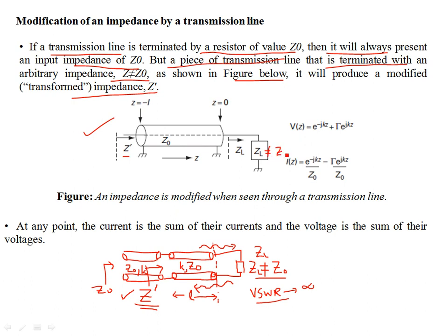Okay, the philosophy is that you see at this interface, and this is z directed, your transmission line is redirected. So at the interface where z equal to 0, you should have the constraint that V of 0 divided by I of 0 should be equal to Z naught.